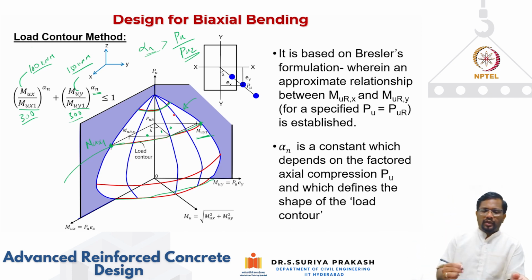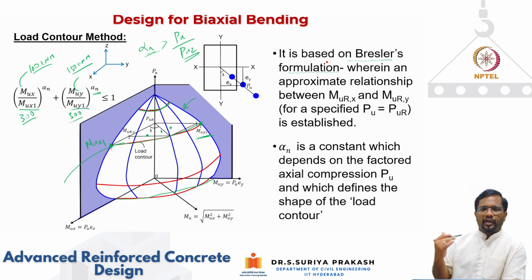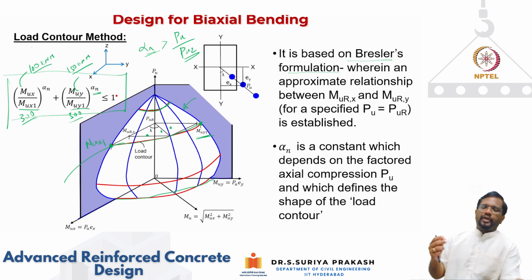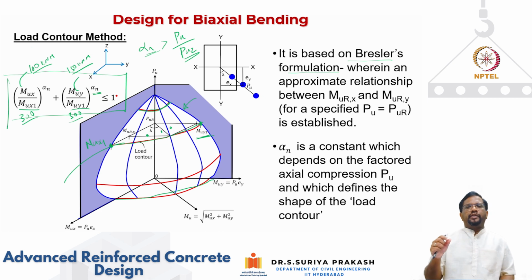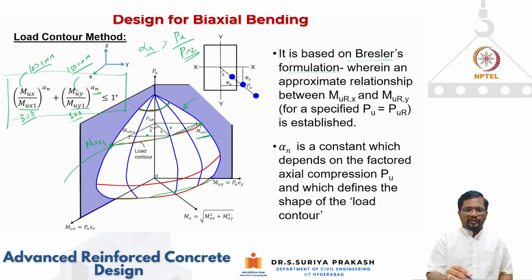Again, this is based on Bresler's formulation. He approximated how the interaction between two bendings is going to happen at a particular level of axial compression. So he proposed this equation, and it is able to conservatively and quickly tell whether a particular demand is meeting the requirement, whether it is safe or not.